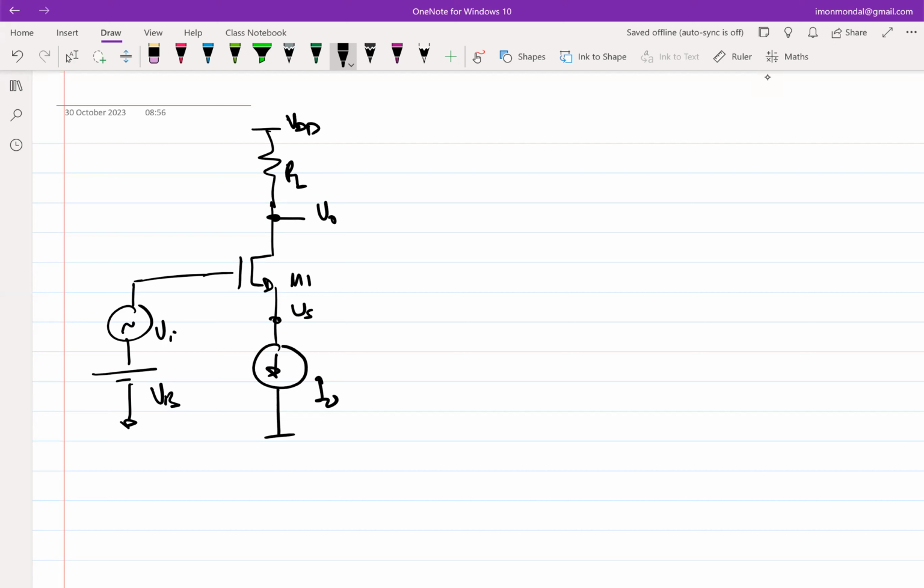So then we devised a strategy. What was the strategy? This architecture biases the transistor using a constant current source, so all the good things of constant current source bias come in. That is, the gm doesn't change with threshold voltage, it is less sensitive to mobility and so on. But it doesn't give amplification, because the source is now changing with the gate. Source is not fixed. Source is not incrementally grounded. So we needed to incrementally ground that.